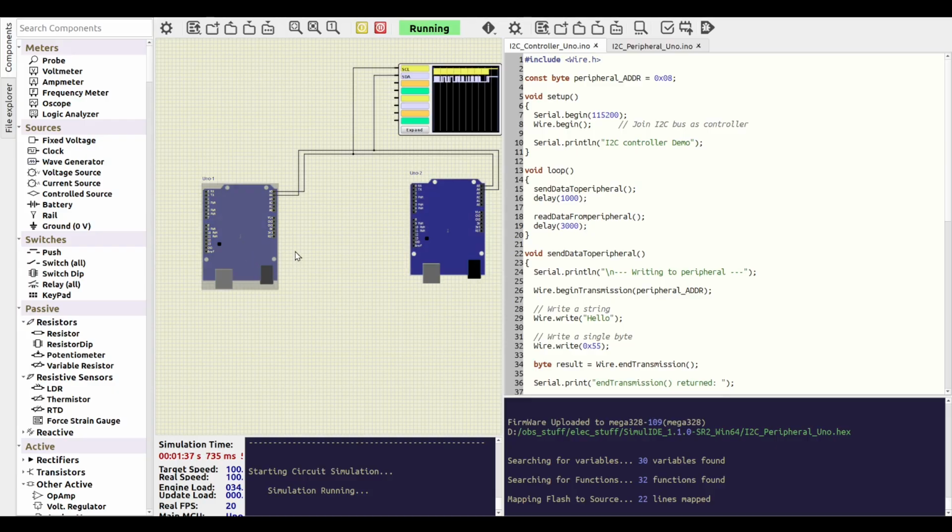All right, well, since we know we're doing stuff to serial monitor, let's take a look. Well, there's the first serial monitor. Here is the second serial monitor, just to show that something different is happening. So what's exactly happening here? Well, it's saying that it's received "hello you", which is what it's sending. And then this is receiving 8 bytes of Uno. Okay, so the final eighth byte is just a space, even though the message doesn't show it. That's just part of serial. So yeah, transmitting back and forth here. Each time it's a success because there's no mistakes.